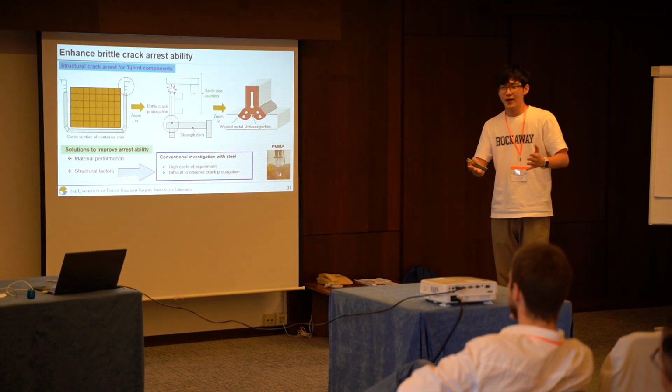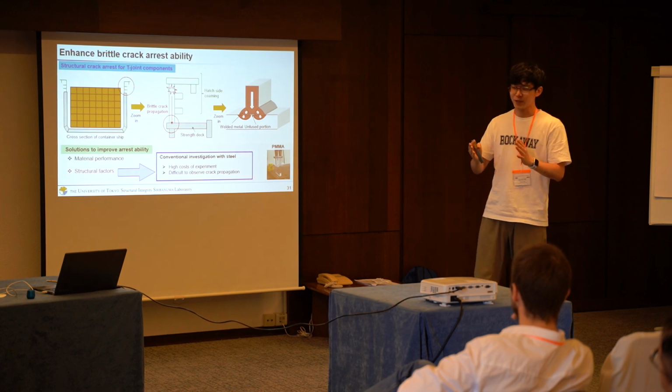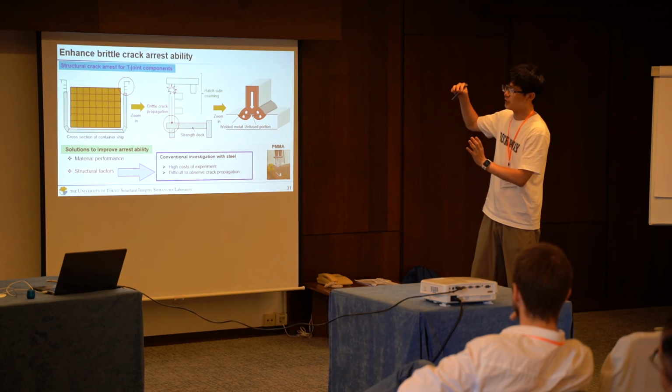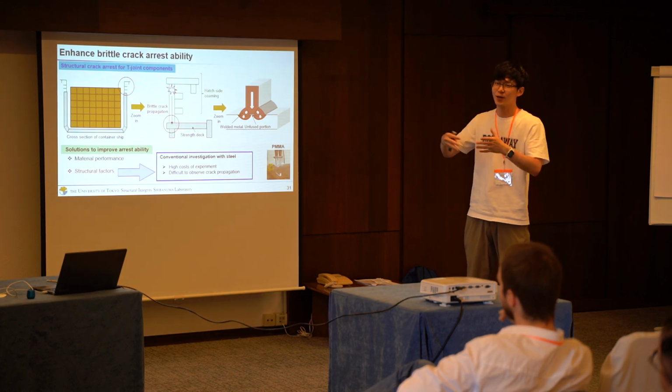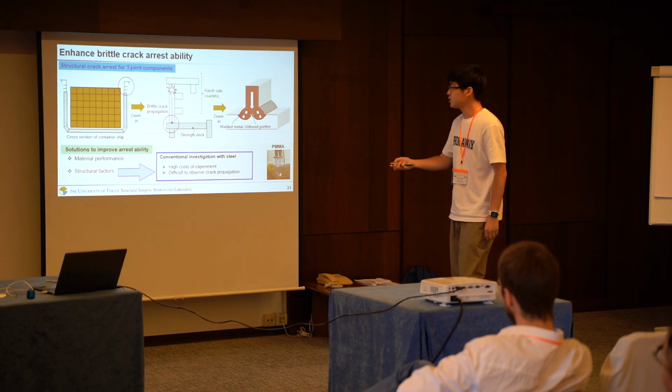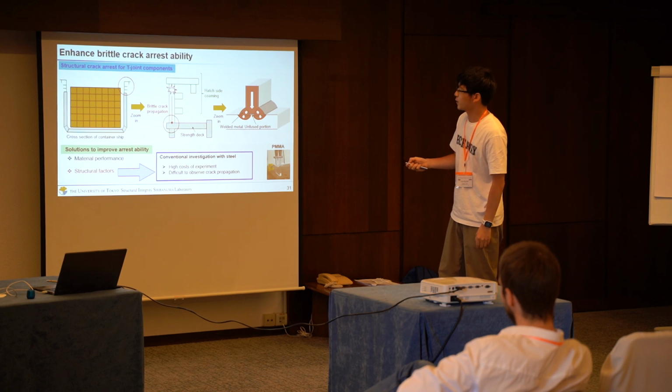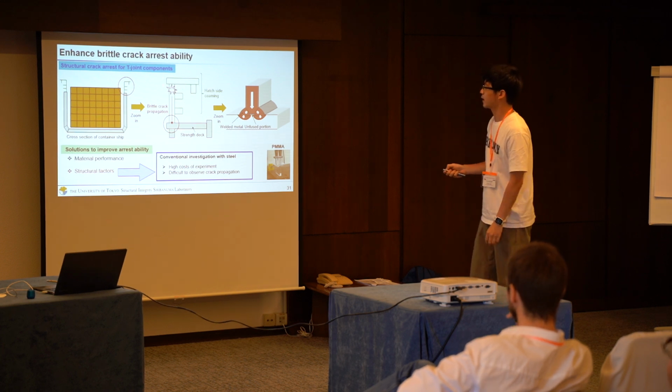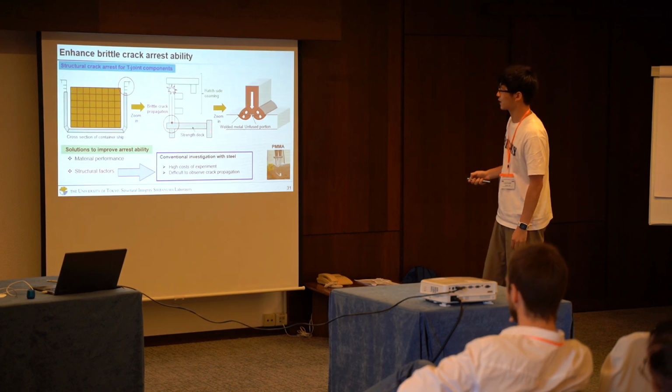As I just said before, the brittle fracture is very dangerous, and we need to investigate. We need to clarify the nature of brittle fracture resistance. Right? And in the container ship, the brittle fracture usually propagates from the hatch side coaming to the deck.